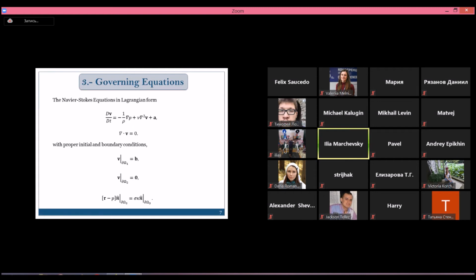Yes, absolutely, because the viscosity coefficient is not constant in this case. Here you need to consider the Cauchy conservation equation, and you model exactly the same, but with that equation, not the Navier-Stokes equation. You take the Cauchy equation, taking into account the change in the viscosity. The numerics go well, but you need to control also the error in the simulation throughout the time step.